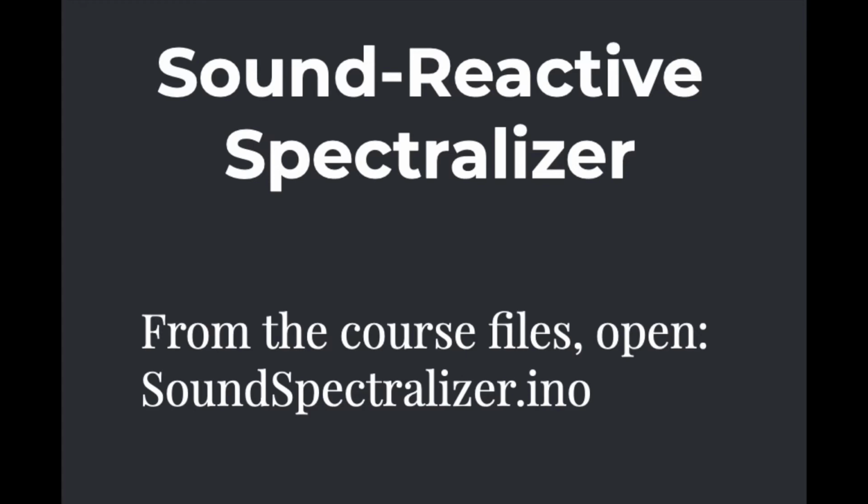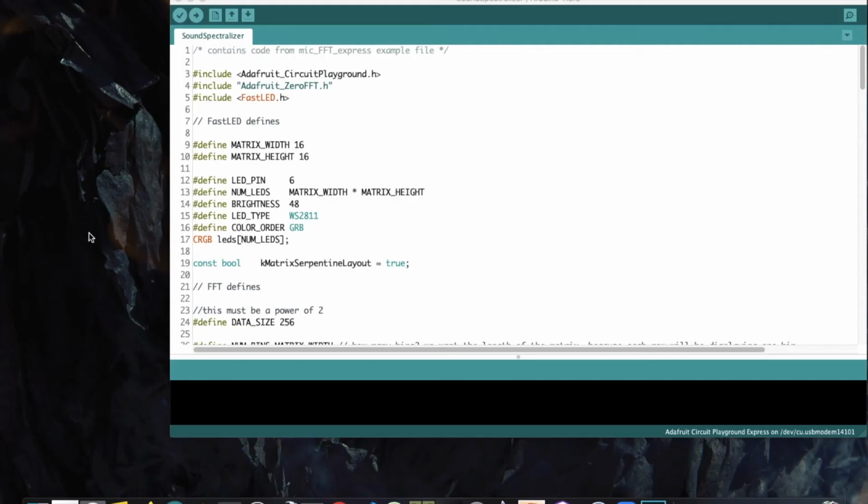From your course files, open up soundspectralizer.ino. In this sketch, we'll learn to visualize sensor data across an LED matrix. We'll build a sound-reactive spectralizer, an interactive matrix lighting project. We'll need to install the FFT library. If you haven't installed it and need instructions, please see the last section, which will show you how to install this library. This sketch is a synthesis of fast LED animation code and the FFT algorithm from the last section.